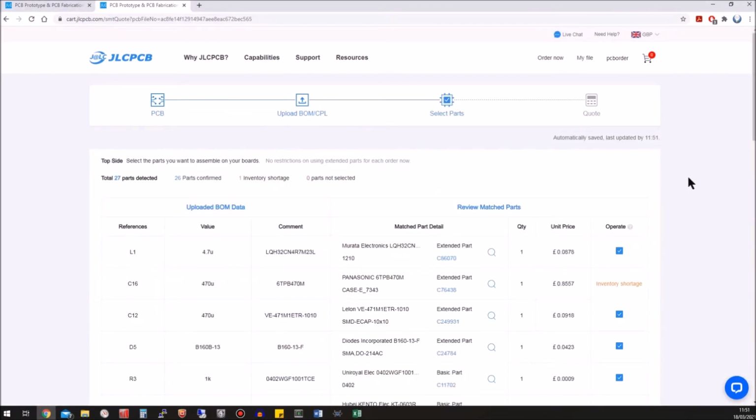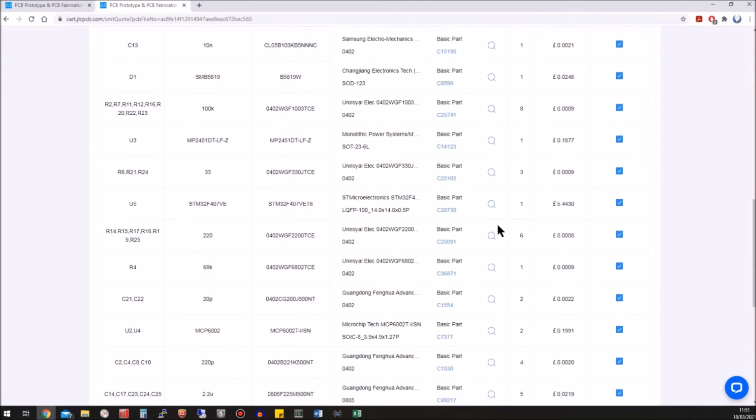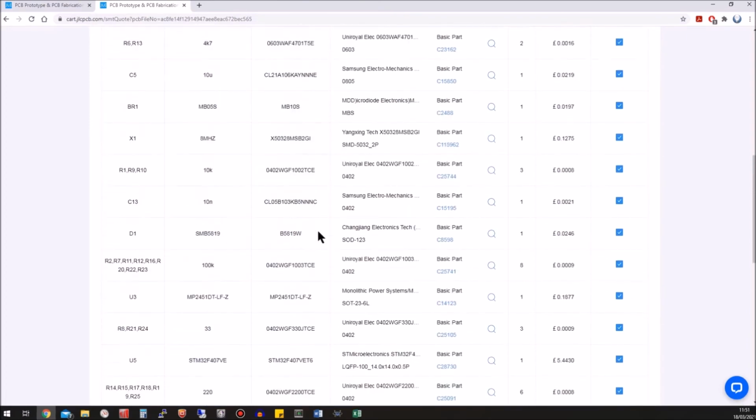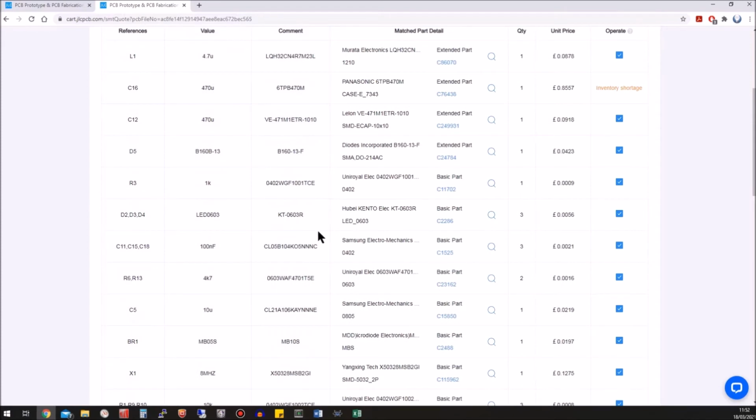This next screen shows which parts from the library have been assigned to each component in the design. Most of them should be correctly selected by default. This is why we filled the bill of materials file with both the stock codes and the manufacturer's part numbers before. Have a quick inspect just to be sure none have been misselected.